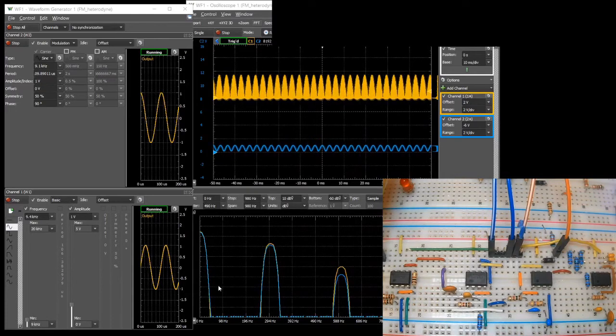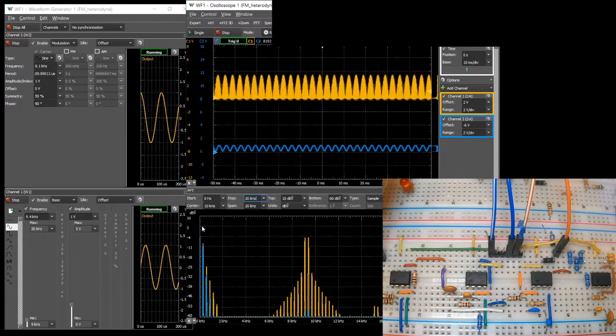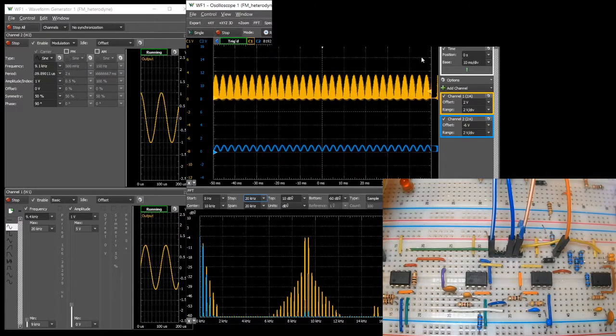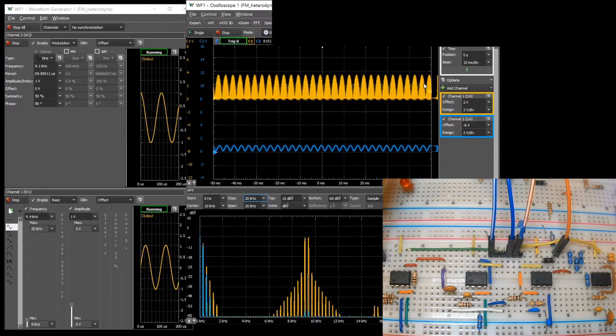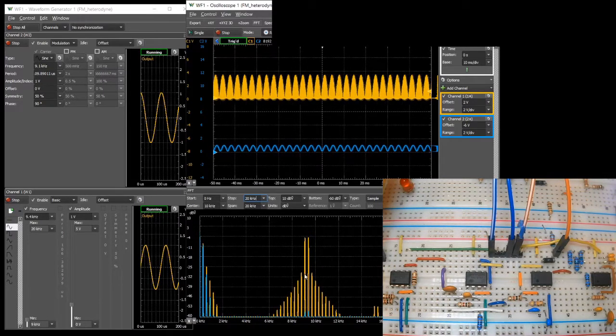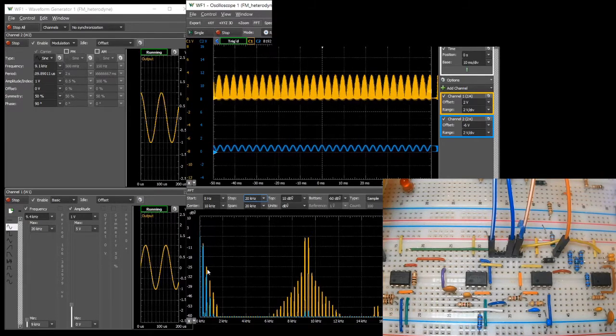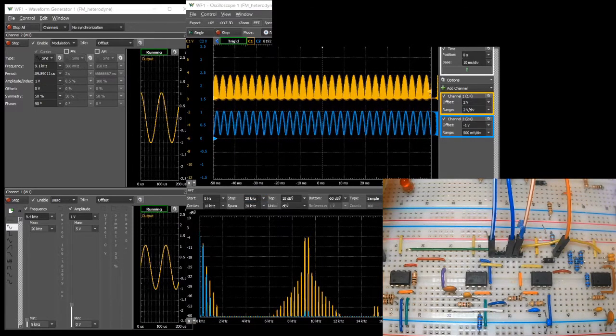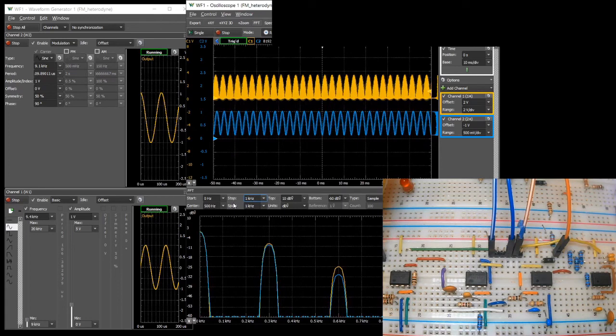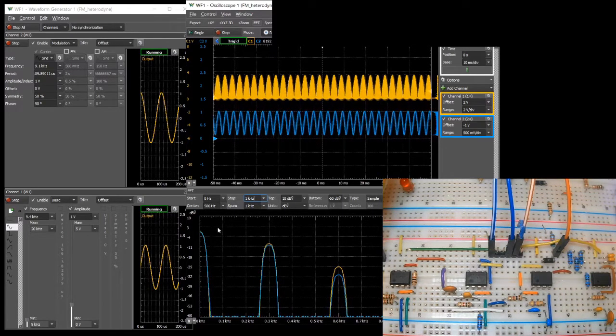The yellow trace is now the signal after the diode, which is input into the low-pass filter. The output of the low-pass filter is represented by the blue trace. From the comparison of their Fourier spectra, it is evident that the low-pass filter blocks all the high-frequency components as expected. The low-pass filter output, the blue trace signal, contains the desired heterodyne component. The second-order harmonic is more than 20 dB lower and not of concern. The next step is to remove the DC component.